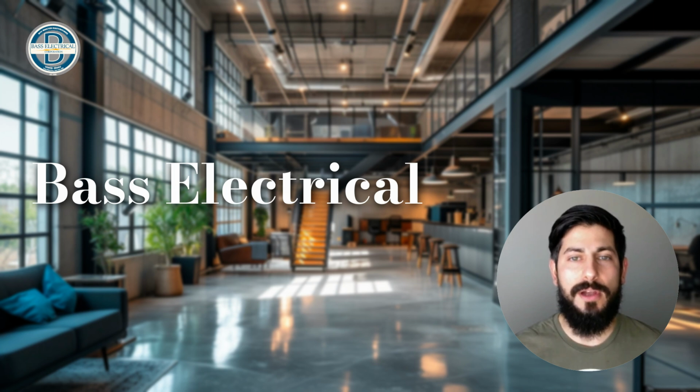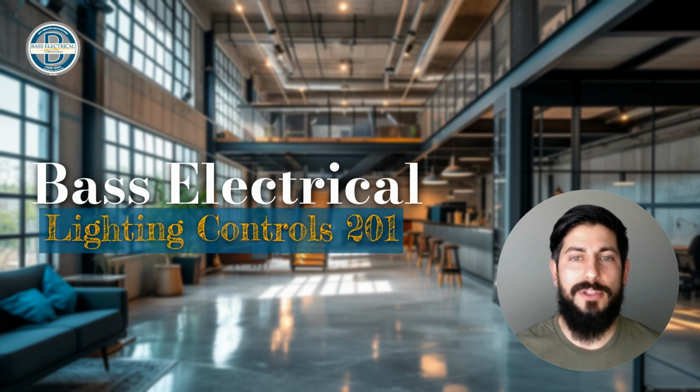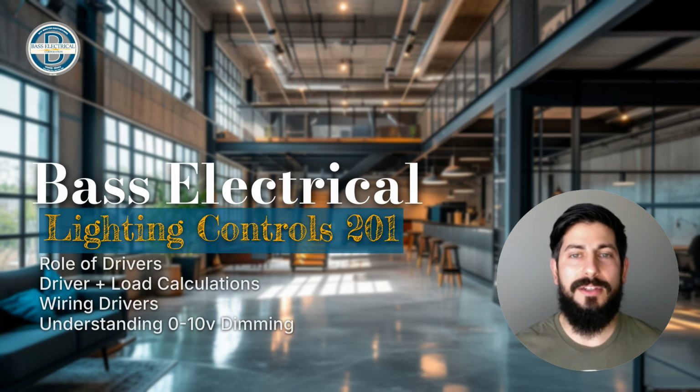Welcome to this tutorial on lighting controls. We will explore the role of drivers in lighting circuits, how to calculate the number of drivers needed, how to wire a low voltage driver with a switch, and learn about 0 to 10 volt dimming circuits and how they differ from a standard lighting circuit.